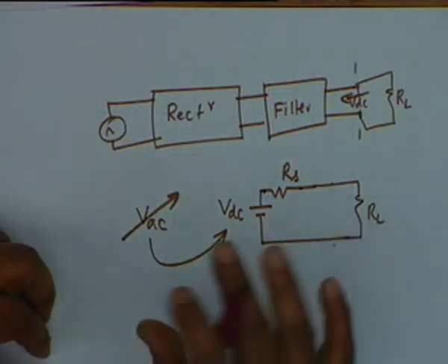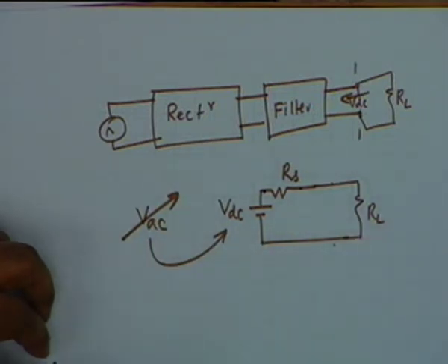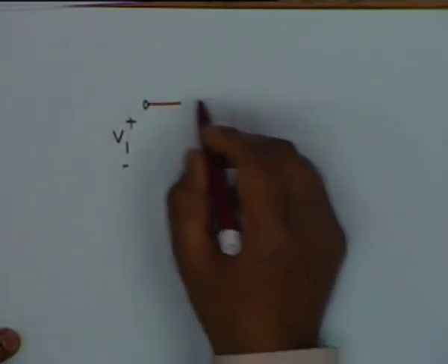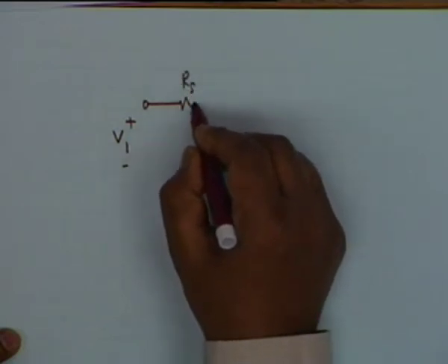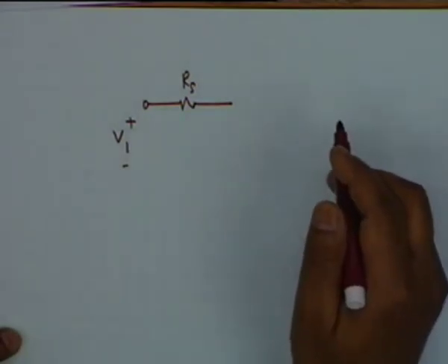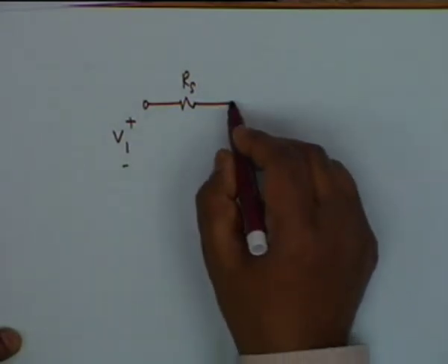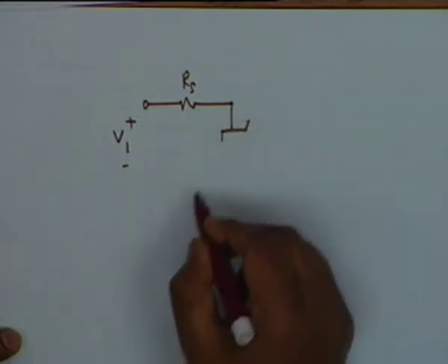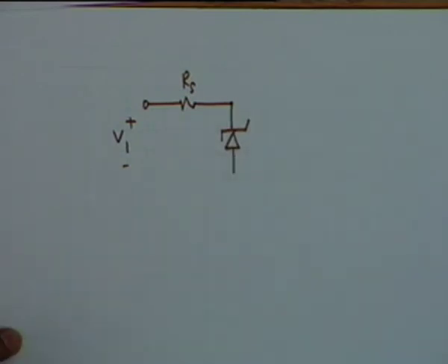To counter both of these, we use a Zener, alright, and the circuit is like this, very simple circuit. What we do is, the VDC source, we call this V1 plus minus, this may represent the source resistance or a resistance connected intentionally. One has to connect a resistance here, and then you have the Zener. The Zener is represented like this. It is represented by means of a wavy line here instead of a straight line. If it is a straight line, then it is a normal diode.